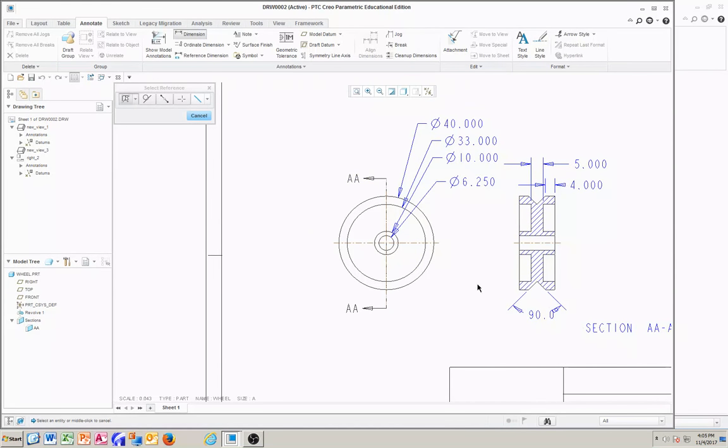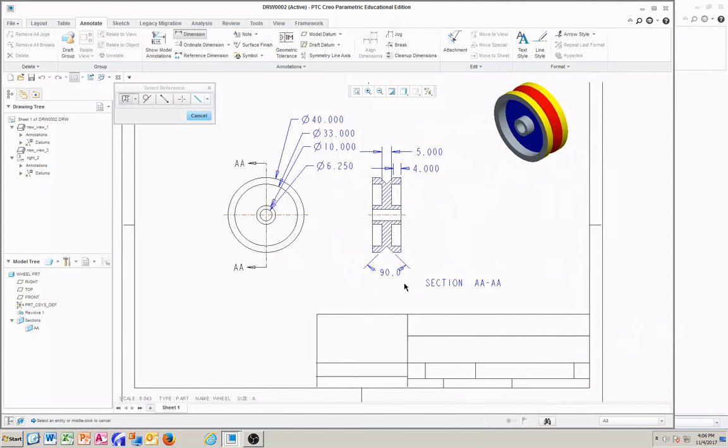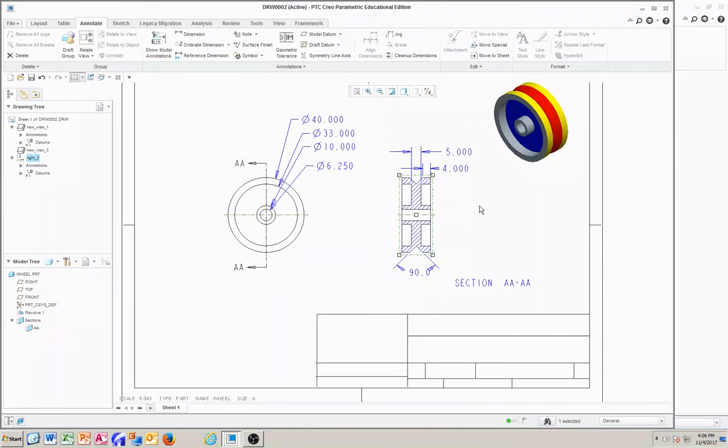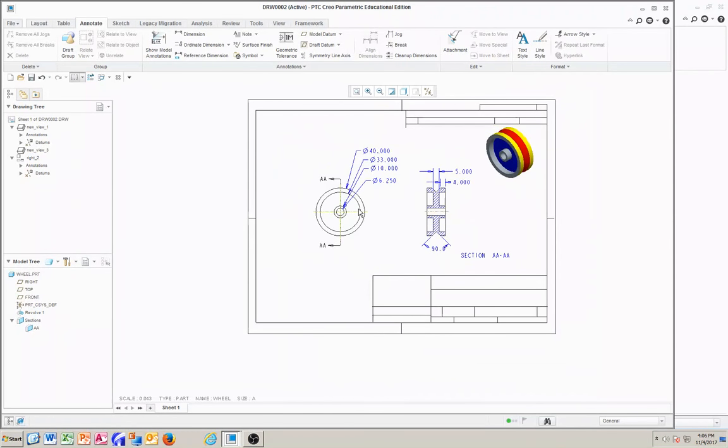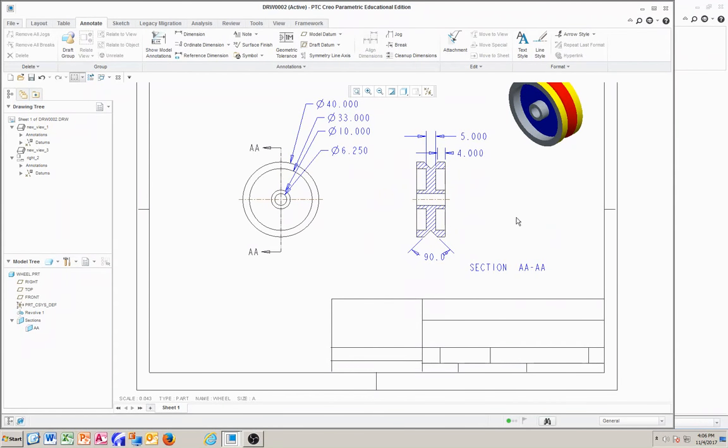And this is causing a little bit of a problem because it's taking up all the space. Let me see if I can do the total. No, I don't need it, because I already know that the diameter is 40. You don't need to be redundant on dimensions. So just move them a little bit to the side. Again, you're going to be using the C-size paper, and you're going to put the drawing for each part on one sheet of paper.